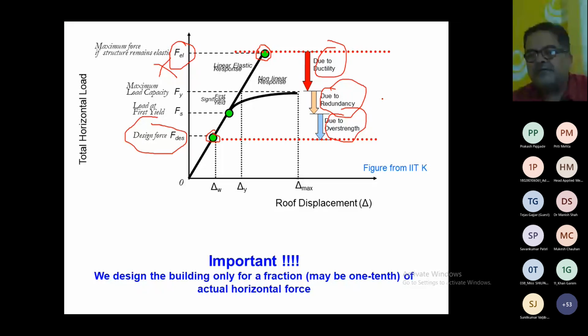We add some standard deviation, and instead of 25, we design for 30, 32, right? We know that on site quality control is not achieved as in the laboratory. So we design for 32 in the laboratory, or 31, and then it will give you at least 25 on site under conditions where quality may not be achieved thoroughly, right?